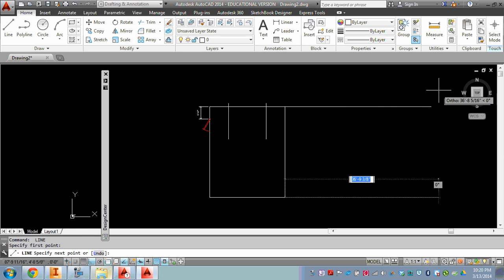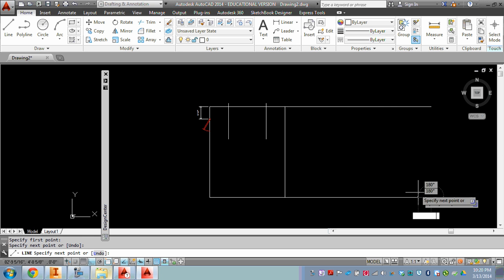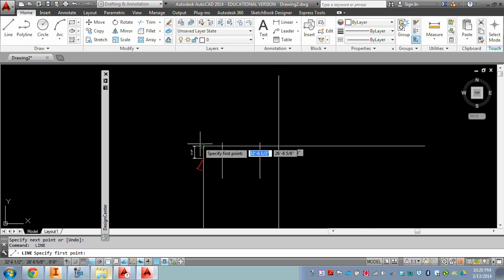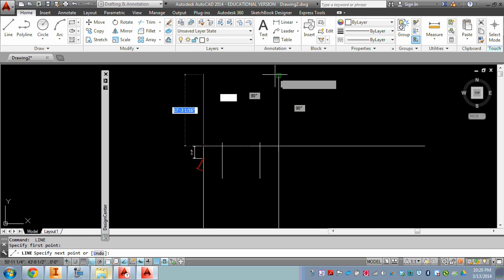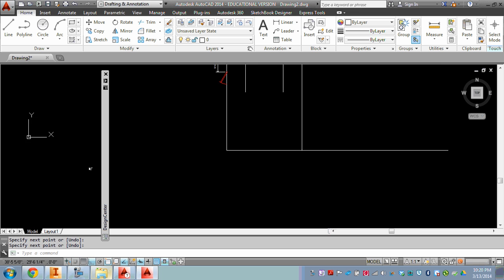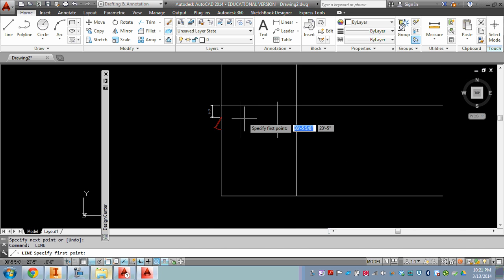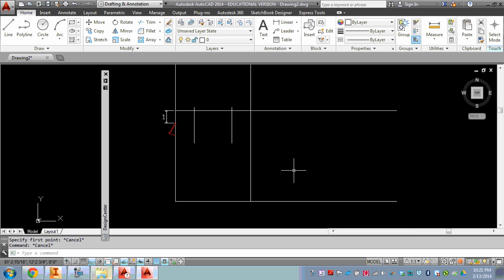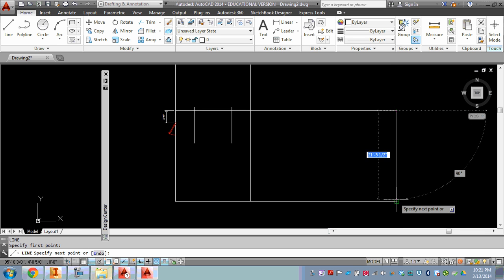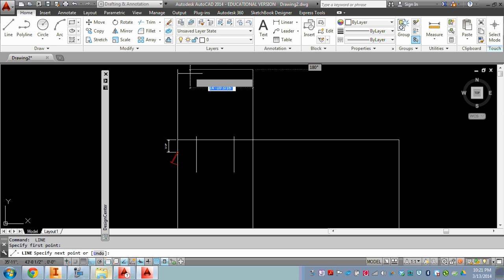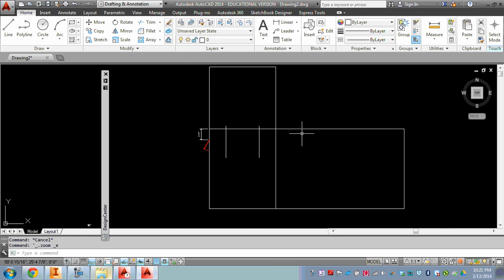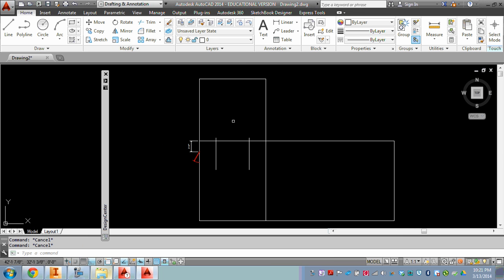Same thing here. Draw a line straight up, another line straight up. And then really we'll hold off on doing the rest. We're going to hold off doing the rest. This garage for right now is going to be 10 foot tall. So we're going to select this point to this point. And these will be pretty much the views that we're going to create our front, or the front of the building. We're going to call the garage front for right now.